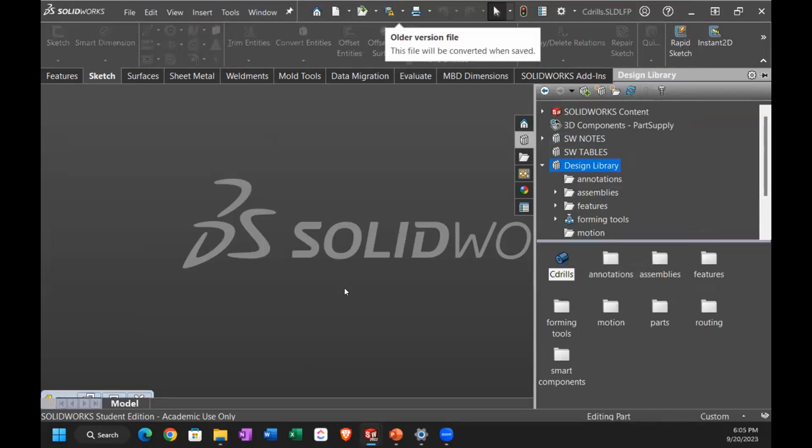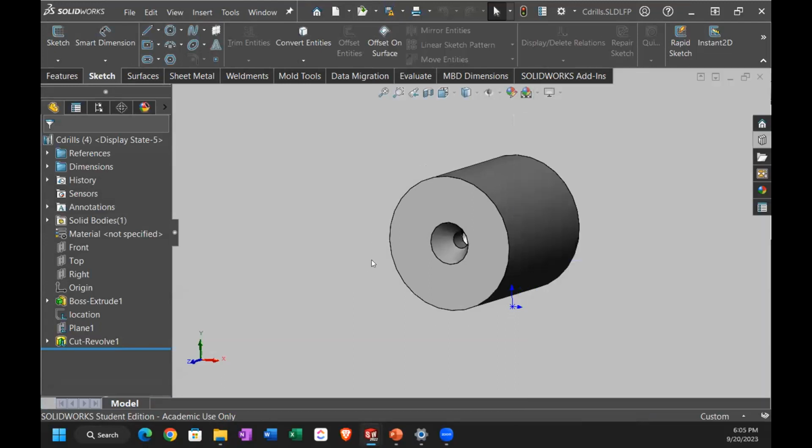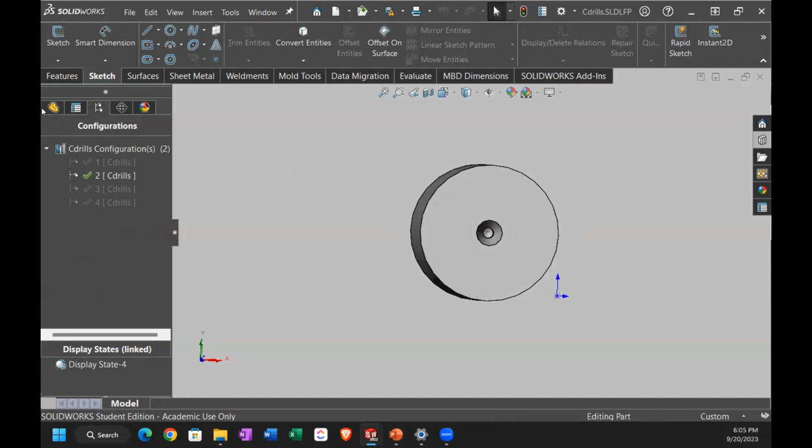And so coming from a manufacturing background, one of the things I want to be able to tell my machinist is that you can put a center drill in the end of this part, and there's all different sizes of center drills. So I went into the Machinery's Handbook and made a number 1 center drill, a number 2 center drill, 3, 4, all the way on the sizes.